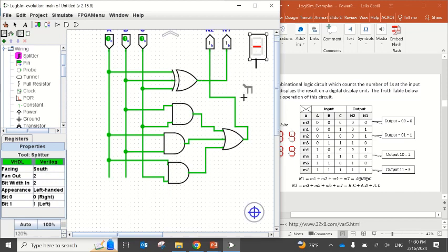and you have to connect basically the thick wire, which is usually in black. So in Logisim, if a wire is black, like you cannot see the color like this one, it means it's carrying multiple bits, which is what we call a bus. Now it's saying incompatible with, so this is when it's orange, it's telling you I'm expecting 4 bits here and you're giving me only 2. So we need to give it 4 bits.